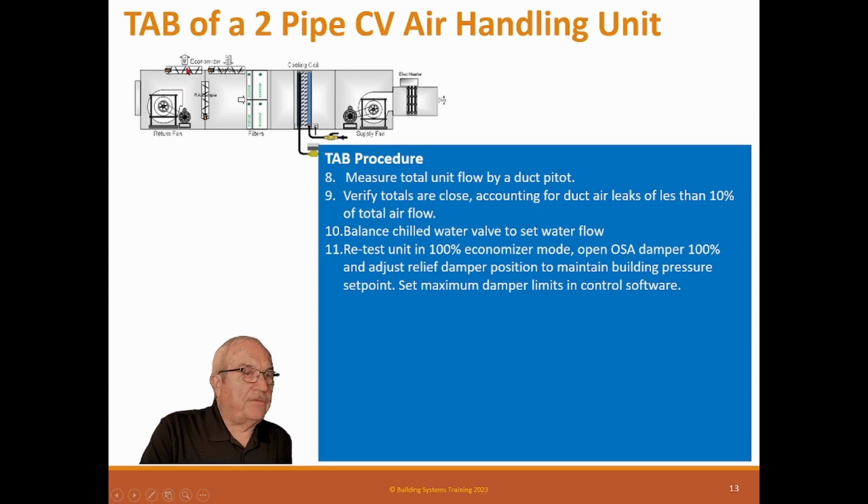So you're going to have to set this damper up so when this fan's on, the economizer, this damper's closed, and this damper's full open, you need to adjust this linkage down to where, or in software, adjust it so with that, it needs to have a setting to maintain building pressure. It's very irritating to have a system that changes building pressure during economizer load and blows the doors open. So it needs to be the same building pressure you had during normal operating pressure.